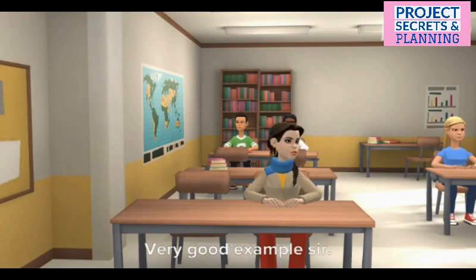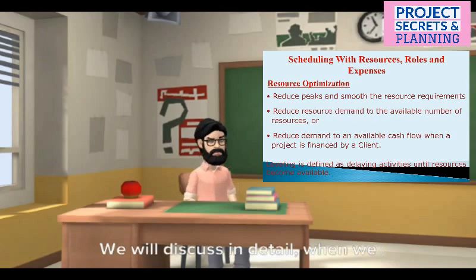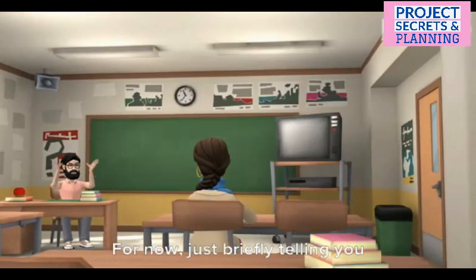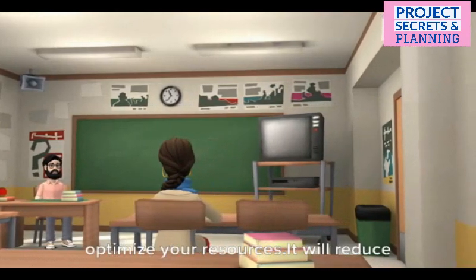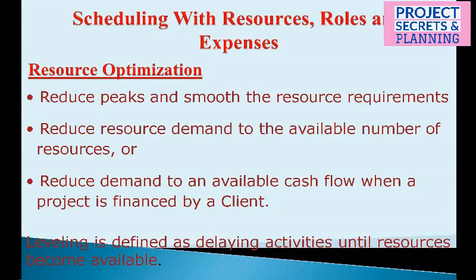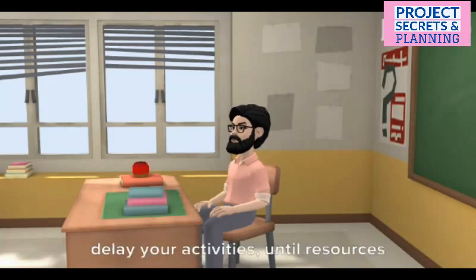Very good example, sir. You can optimize your resources as well. We will discuss it in detail when we reach that topic. For now, just briefly telling you that from the leveling option, you can optimize your resources. It will reduce peaks and smooth your resource requirements, and reduce resource demand to the available number of resources. Reduce demand of cash flow. It will delay your activities until resources become available.